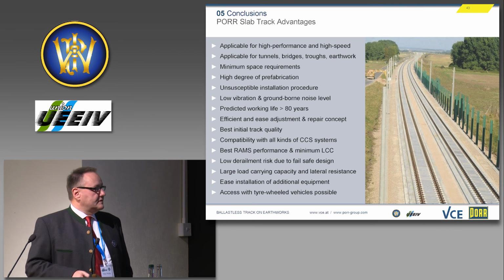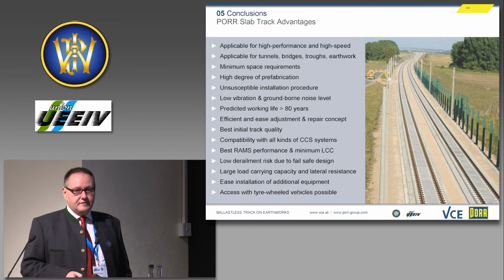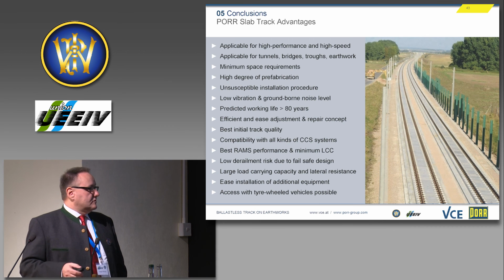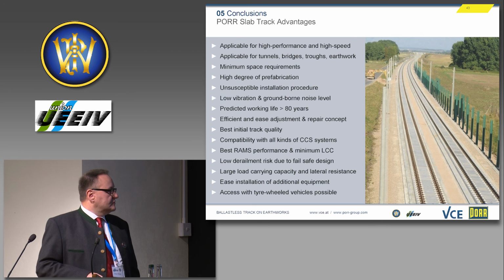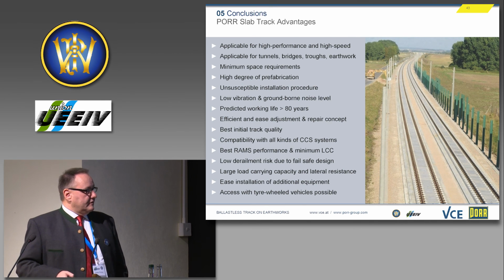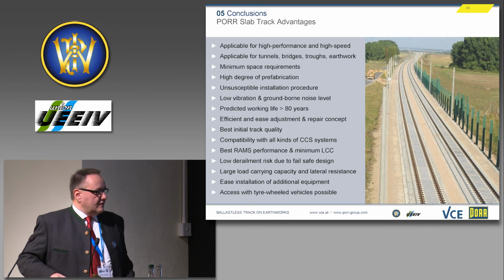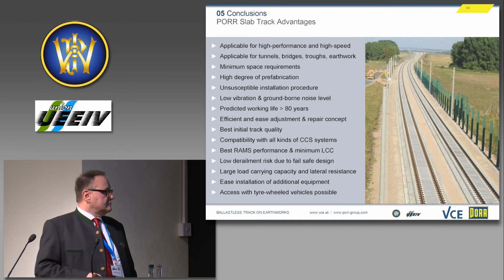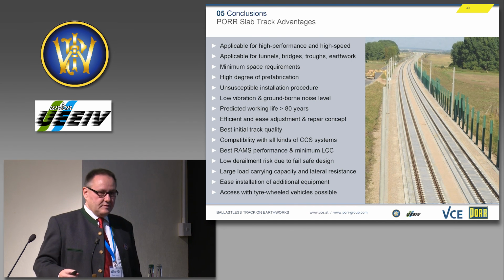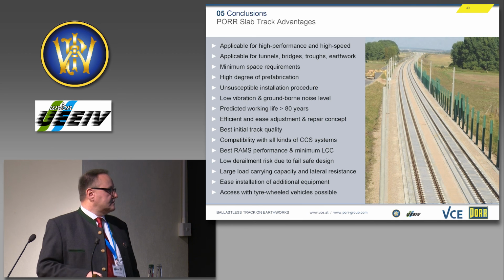So Balise can be installed on top of the slabs, also Indusi and all kinds of other systems. Life cycle costs are low, and we have a low derailment risk due to this design, so that even in case of a derailment, the vehicles are still guided along the rails, especially when we implement these additional elements.